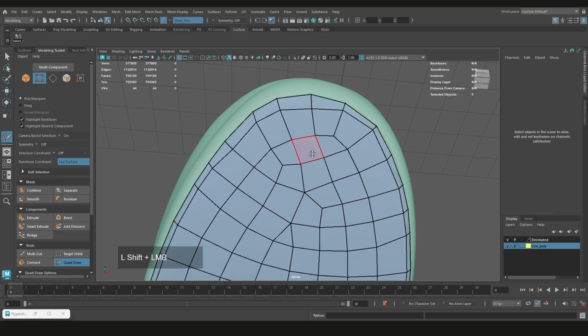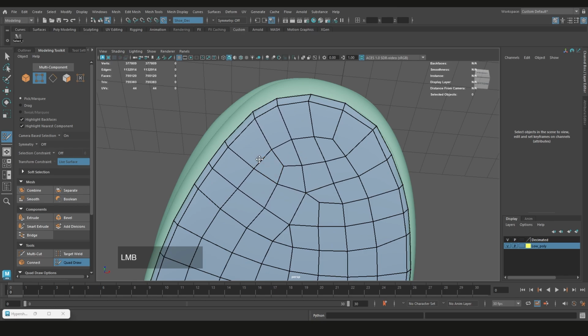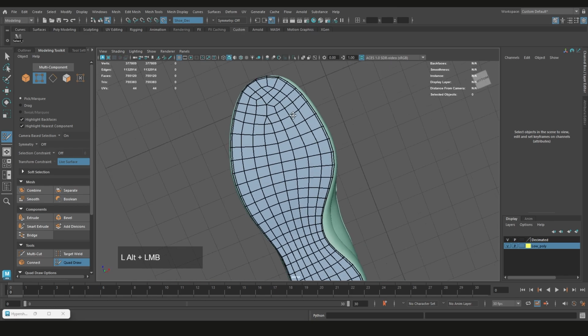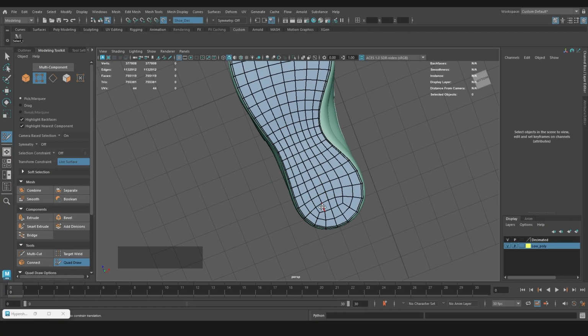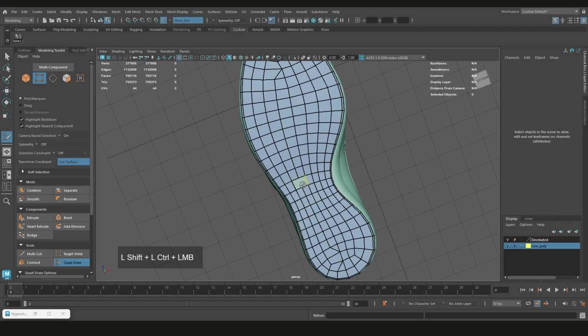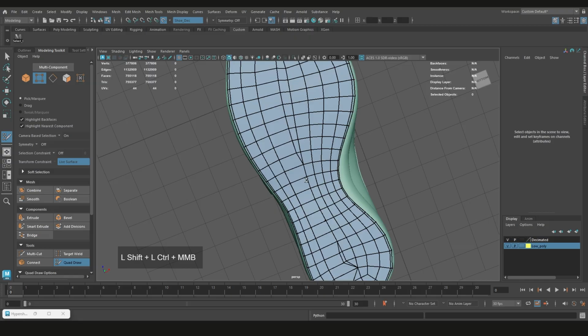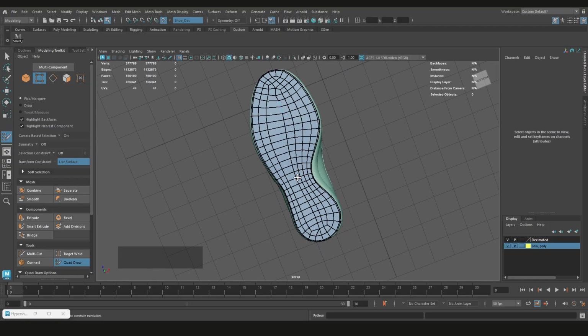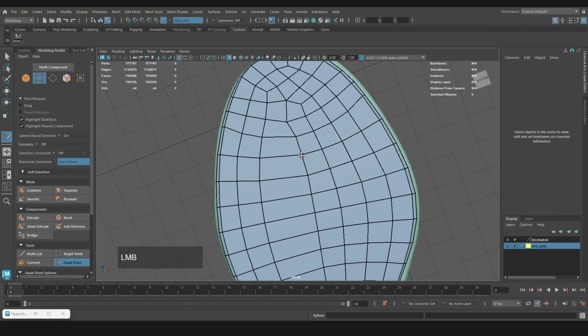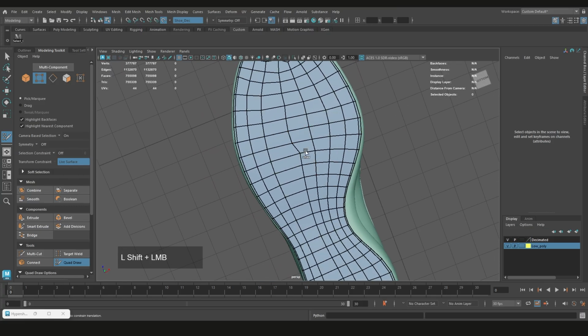So there's ways to figure this thing out. There's no need to, but again, it depends on what you want and how much time you're willing to put into it. And I put in too much time here, so we'll leave that alone. And we can collapse these edges here, for example. So I'd probably push these ones here, right? Because there's no need to have this many edges. Whoops, this many edges. So I'll just see if that will work. There we go. So to do that, I held down Control-Shift and then middle mouse click and drag. Okay, there we go. And then just Shift-click to smooth.